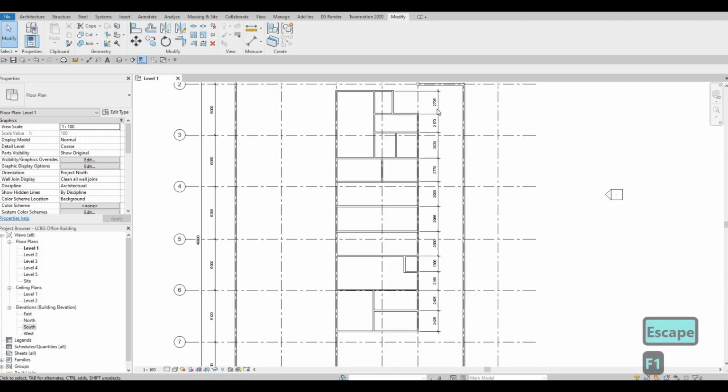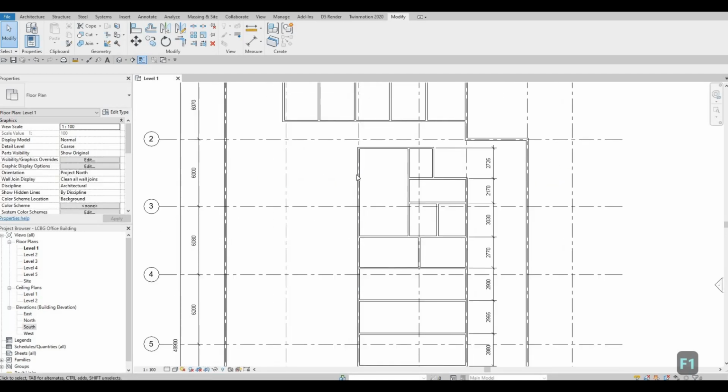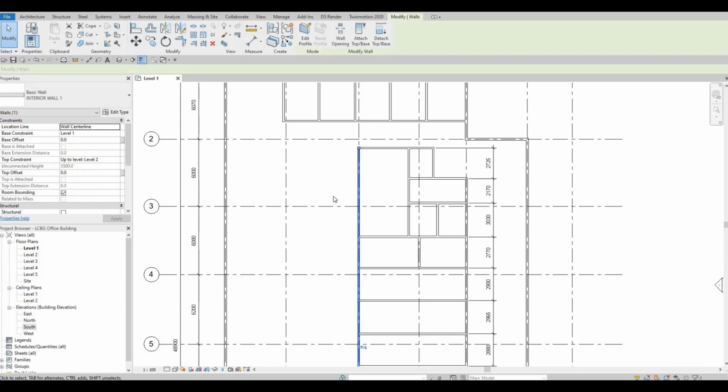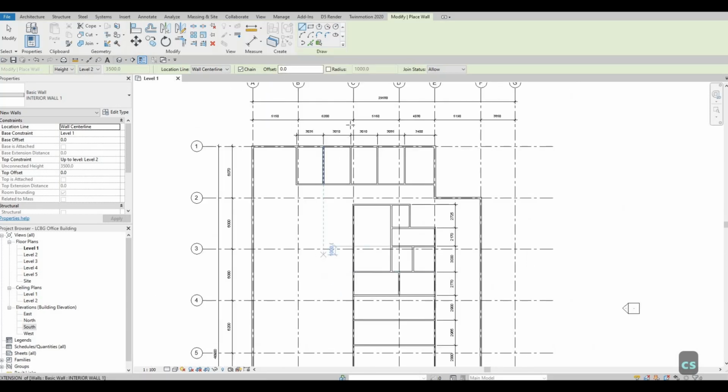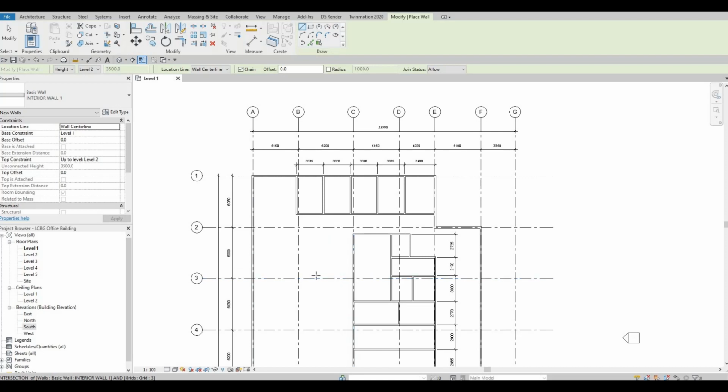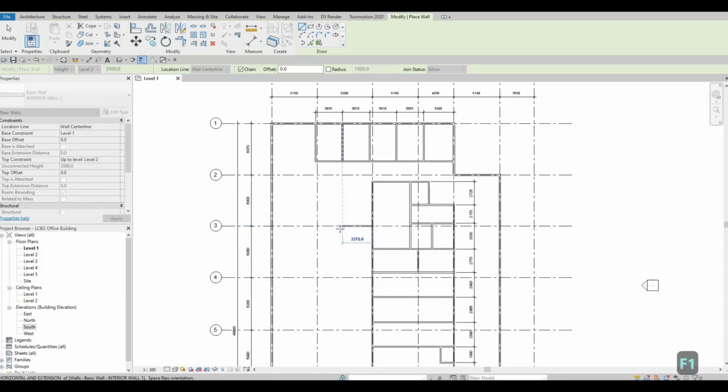I just want to pause a bit so that you could pause the video and then you will see the dimensions of the walls here. So let's get started by clicking on the wall and typing in CS. That's create similar, and let's go to C3. So from C3, I want you to click on, going on the left side and typing in 1680.